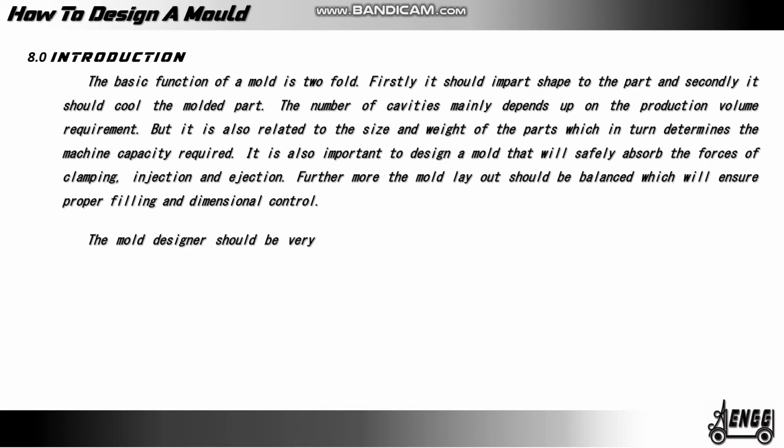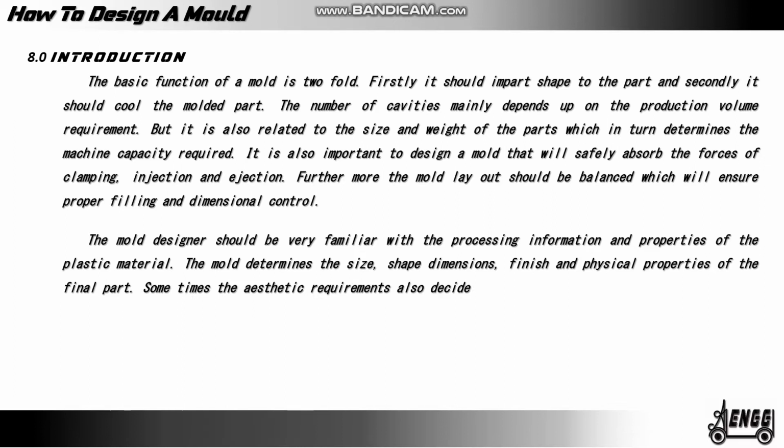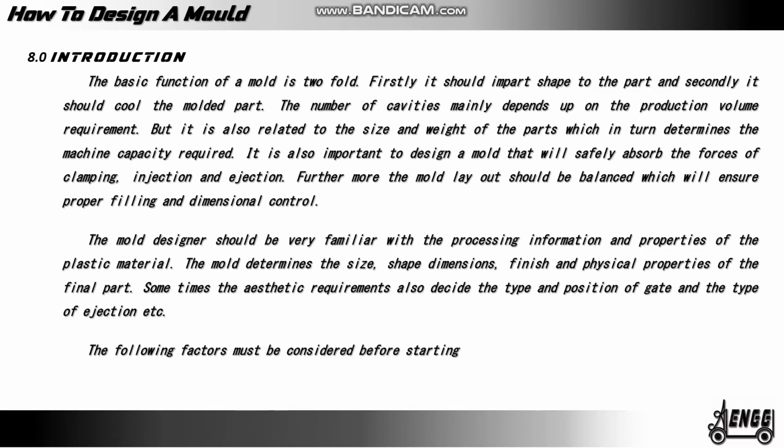The mold designer should be very familiar with the processing properties of the plastic material. The mold determines the size, shape, dimensions, finish and physical properties of the final part. Sometimes the aesthetic requirement also decides the type and position of the gate and the type of ejection, etc. The following factors must be considered before starting the actual design of a mold.